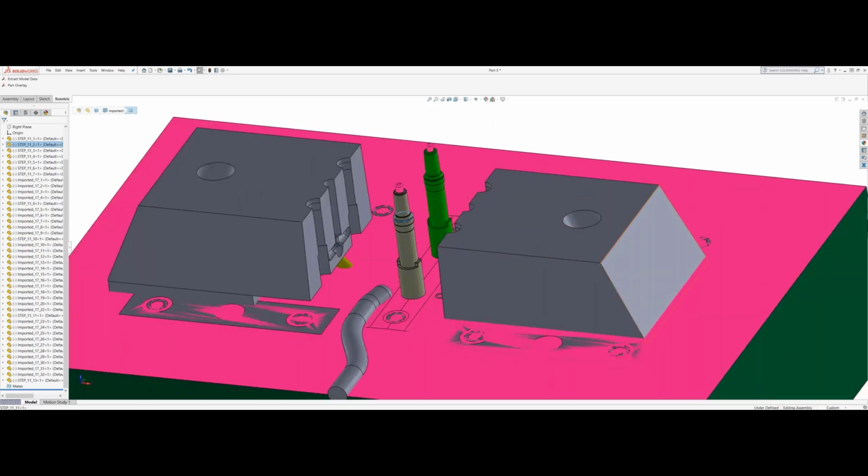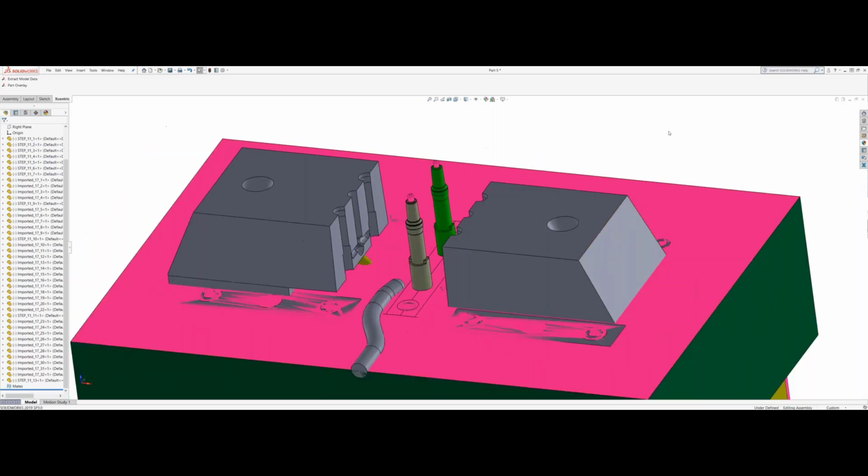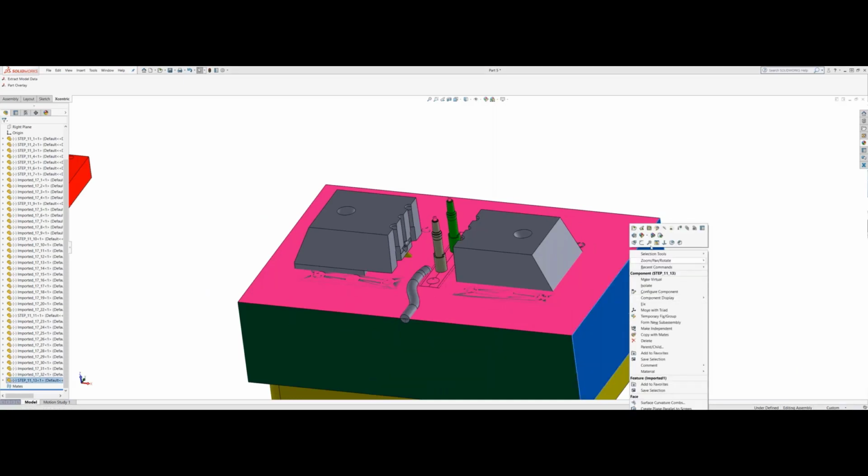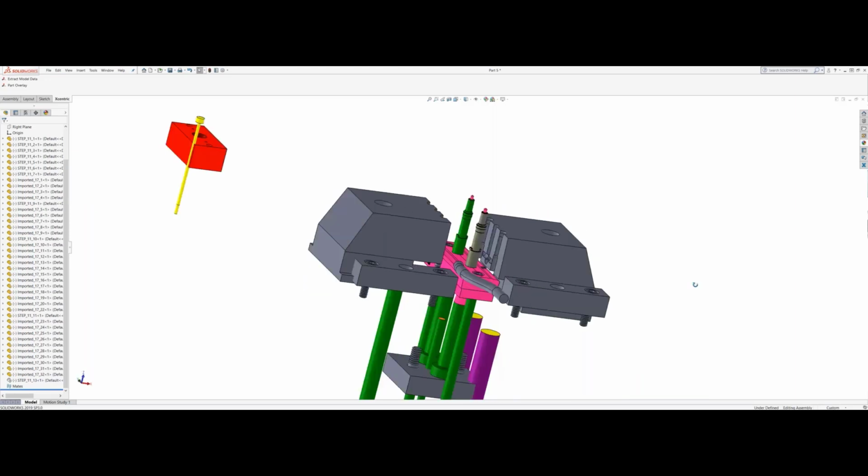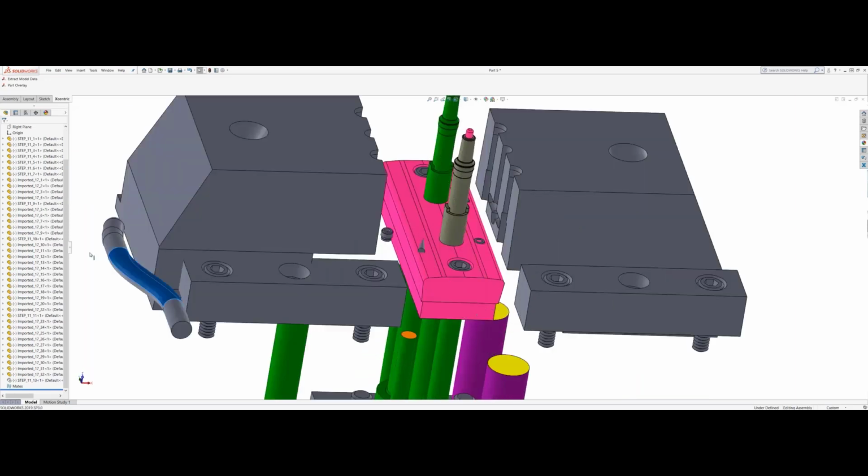All right. Why did you use a stripper plate instead of a sleeve KO? Simpler for manufacture. It's just a plate with pins on the back side. That plate simply has that outer diameter wall stock on it, and we just push that plate straight up and it strips them both off. It's just a simpler design, easier to manufacture, more cost effective.